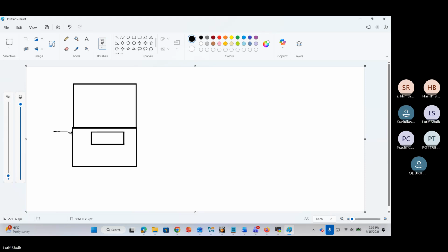Next, you connect the power charger to try to power on the laptop, but the laptop is not powering on. Earlier it powered on, and now it is not turning on. So where is the issue? Check the charging LED on the charger side. Is the charging LED blinking or not? Check whether the charger LED is blinking or not.